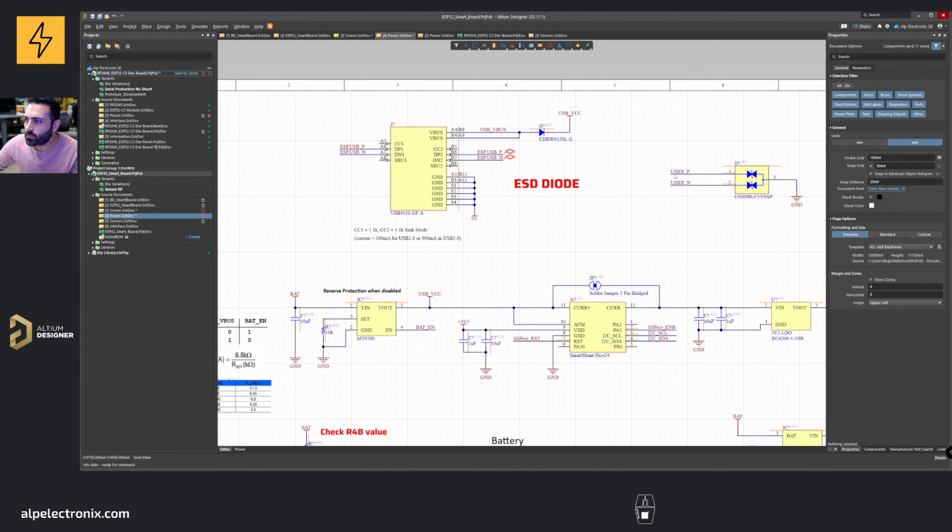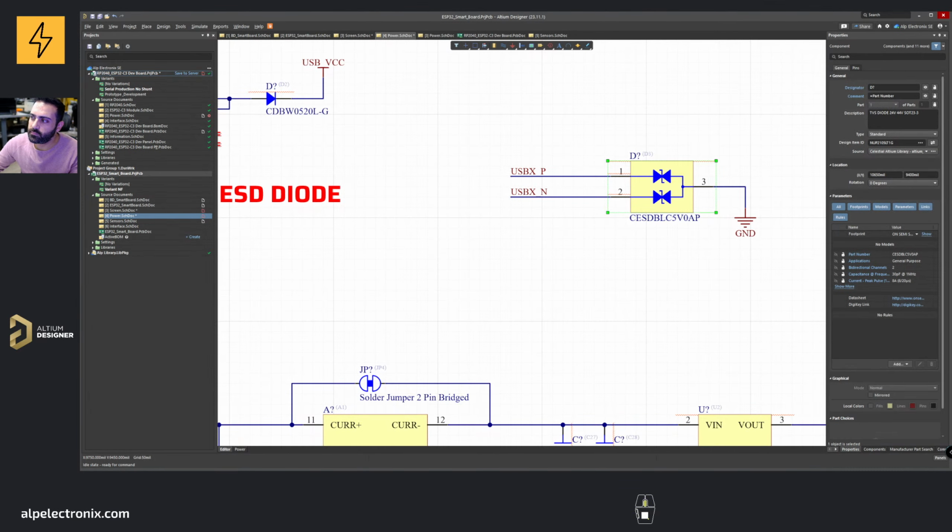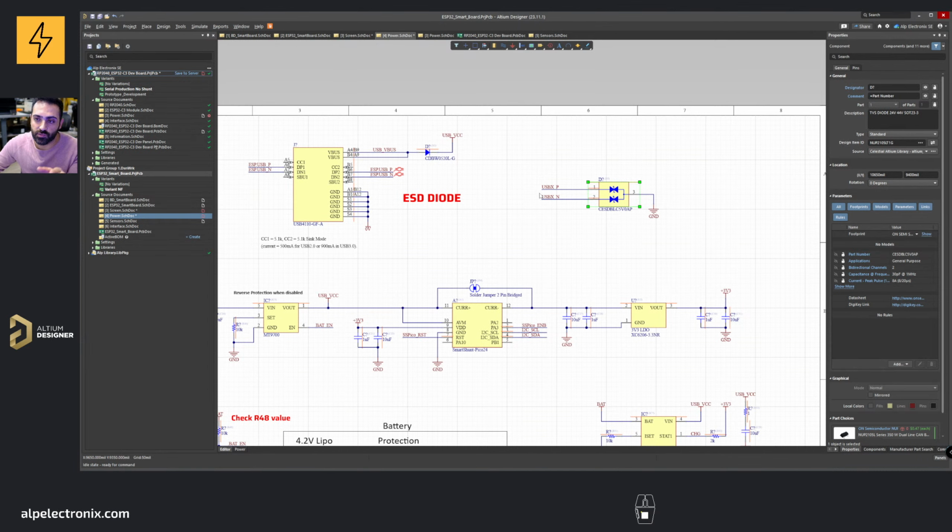Anyway, so we should have these ones. Yeah, and so when you touch the connector, usually the pins are exposed to this electrostatic energy, and if you don't discharge or dissipate it, the pins connected to this USB will be damaged. That's why you need to protect it by using a TVS diode. Basically, TVS suppresses these transients.